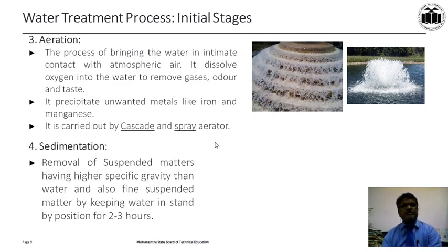Now, the next process is sedimentation. Sedimentation is the process of removal of suspended particles which are heavier than the water under the gravitational force.